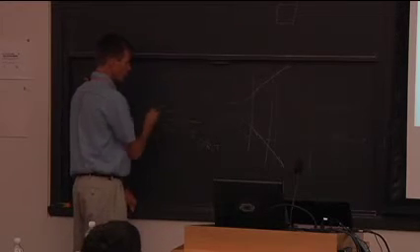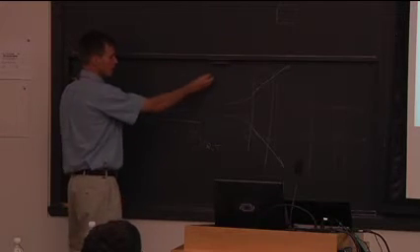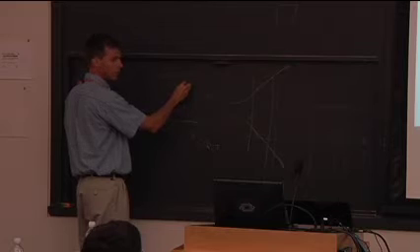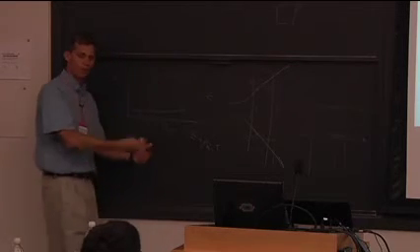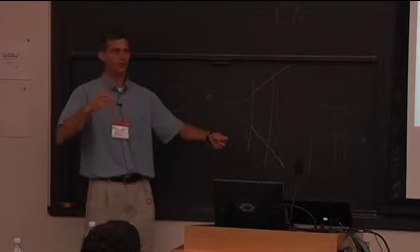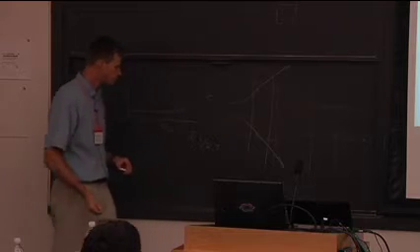Now, when the S-curve gets stretched out, you have no extinction, no ignition. It just says, well, as I decrease my Damköhler number, I just get less and less reaction. It's basically a chemical reactor. I give my combustion a little more time, I get a little more product. I don't have these abrupt switching on, switching off events, which we're also familiar with, right?